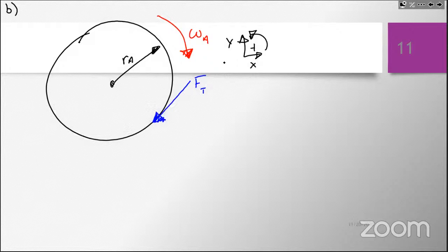So this force is going to produce some rotational work, right? Because as I push it on the bottom, it's going to cause a rotation. And so I need to know what that moment is, and I need to know how much angle this goes through. Well, how am I supposed to figure out the angle that this moves through? So let's write down our equation: T1 plus U from 1 to 2 is equal to T2.